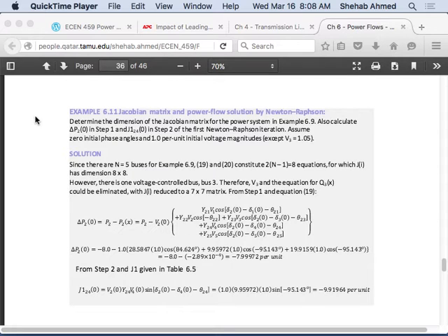the only additional thing that you do with a 2 iteration problem is find the new estimates, right? You will find the new estimates for your values of voltages and angles. Because at the beginning you have to start by finding these power mismatches, or I call them sensitivities. The power mismatch is the difference between the power that you know at a specific bus and the right-hand side of the summation of the power in the power flow equation. So you start by plugging in your current values for voltage and angle and find the power mismatches. If the power mismatches are all less than your convergence criteria, you stop.